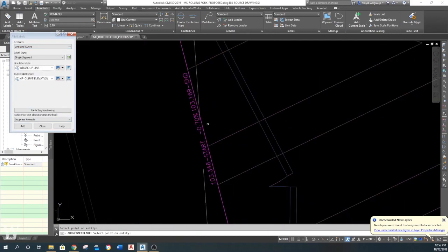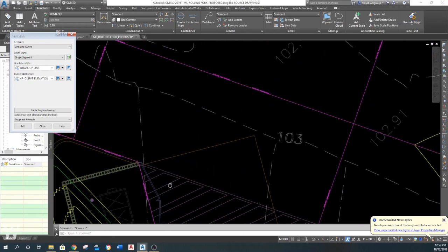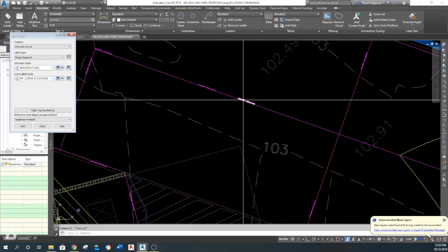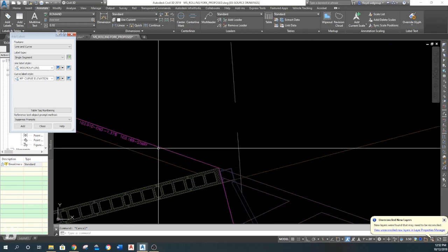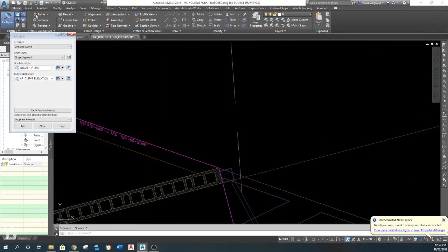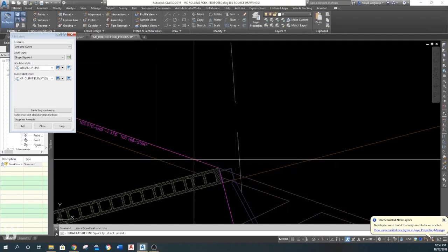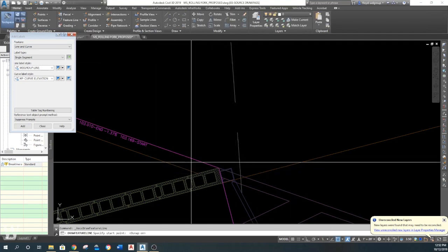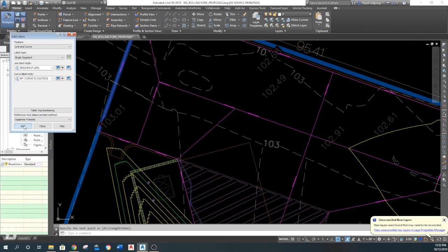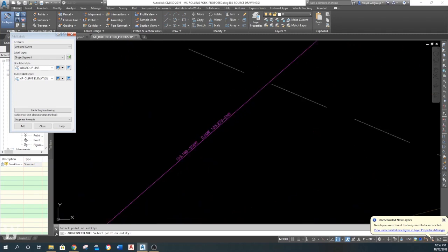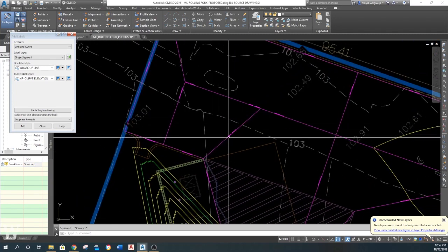Elevation here is 103.1, 103.2. So water's going to wind up coming back this way. But if it comes back this way, I need to see what slope that water is going to come to, because it's going to want to go right here. Turn my snaps back on. 103.169 to there. See what that was. That was at 0.5%. So that should work.